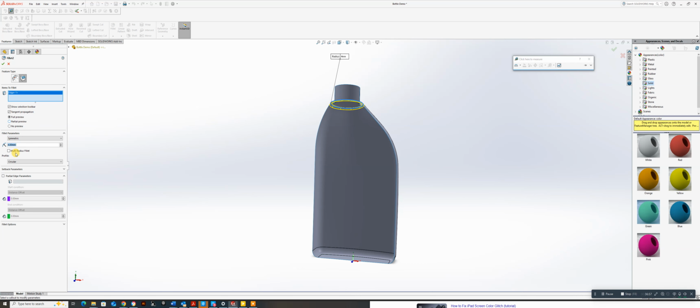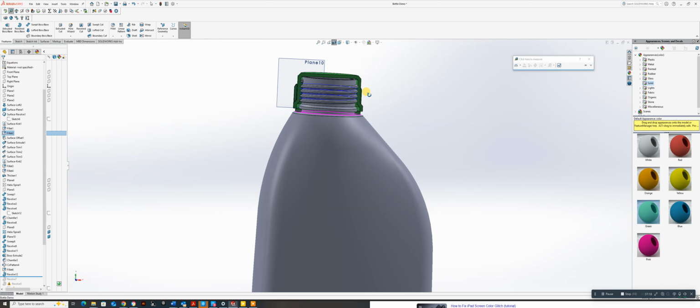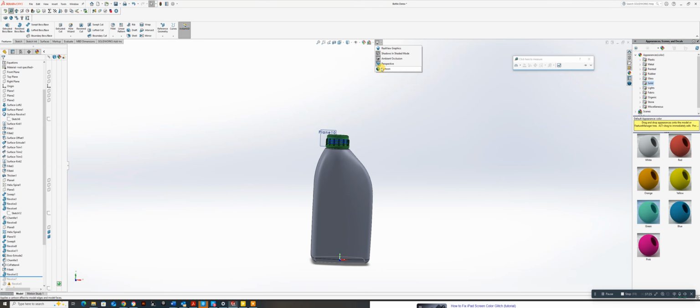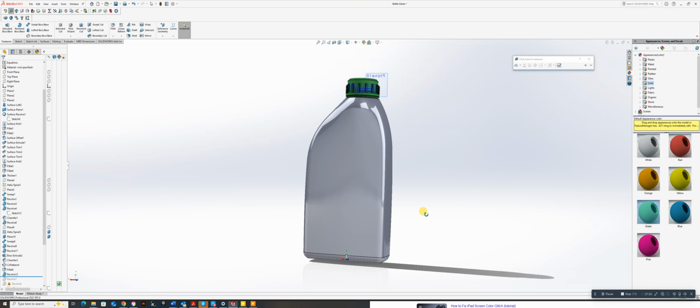So I've got a fillet there of 4. Let me take that down to 2mm. That might make it just look a little bit tidier on that there, and then I'll be happy. So hopefully in the next video, yeah, that looks a lot better, more consistent to it. Let's just go that back, and let's put some perspective on, and let's have some real view graphics on, and there we have a little bit of shadow and the bottle.